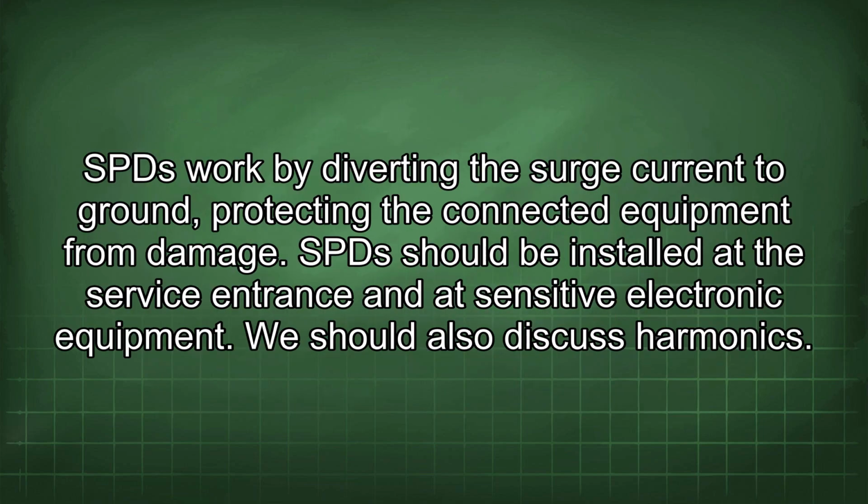SPDs work by diverting the surge current to ground, protecting the connected equipment from damage. SPDs should be installed at the service entrance and at sensitive electronic equipment.